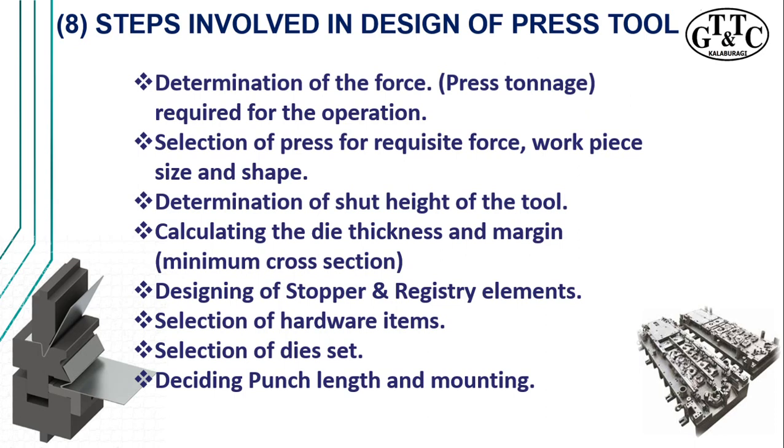Then calculation of the die thickness, and then further, once the die thickness is finalized, and based on these references, all the other parts of the plates, the plate thickness, can be finalized, and then designing of stoppers and registry elements, and then selection of the hardwares such as Allen screws or CSK screws, dowel springs, whatever is required.